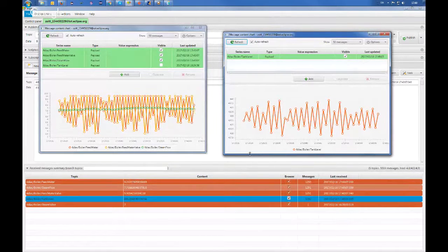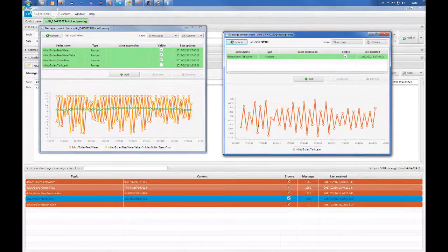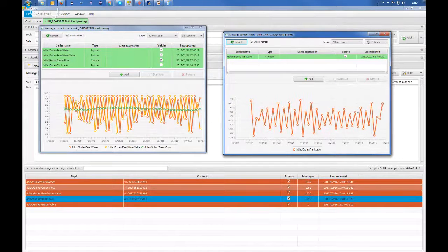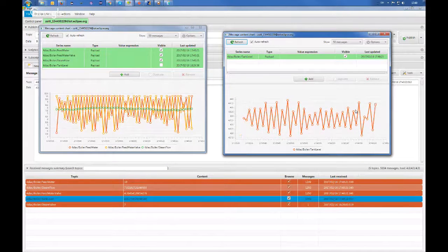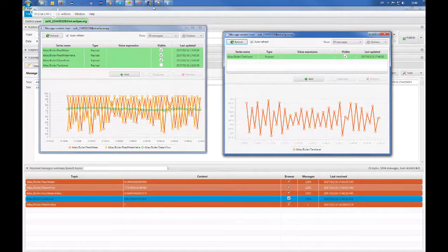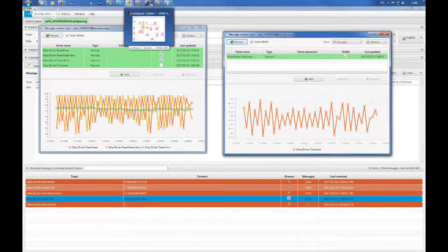I can see that the tank level should be 525 or so, or 550. So there is definitely an issue with this tank because it should have reached the tank level quite some time ago. So there needs to be some tuning of the parameters. Maybe a set point is not correct, or a parameter of one of the values is not correctly set.